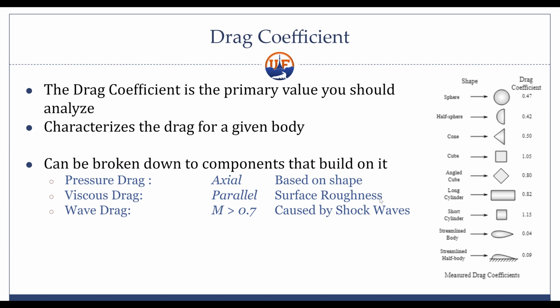So yeah. Why is it not one of those figures on it, but why is it still below that? Okay, so it's actually from Mach 0.7 to Mach 1. After that, there are effects similar to wave drag, but it's mainly when you're going through that transonic region that those wave drag effects are happening.